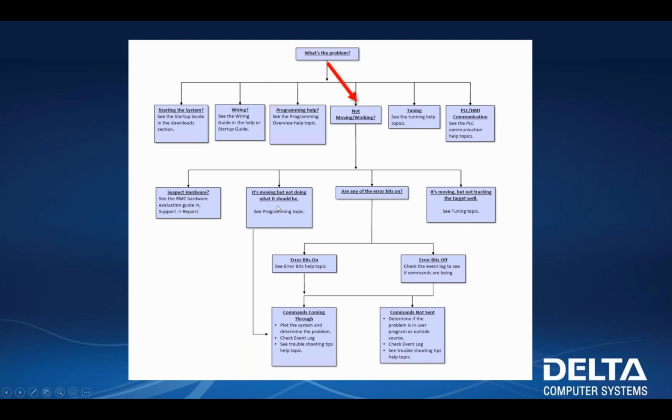it's moving but not doing what it should be. Well, that's not the case. It didn't move at all. It halted as soon as we started. Do we suspect hardware? It could be, I mean, possibly, but generally if you're getting a halt, it's not going to be a problem with the RMC hardware. It's definitely not moving. So what we have to do is check and see if any of the error bits are on.